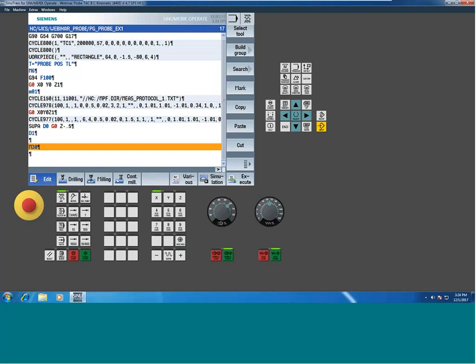From the CAM perspective, I get asked a lot about measuring a bore or a boss or aligning a fixture offset to the center of that feature. Can you discuss if that is possible and how the G-code would look? So that was probably written before I showed the measure command, or even just using some of the primitive commands. But keep in mind, if you're going to start to daisy chain multiple cycles together, that's where you're going to want to use the OVR variables. Grab the data and write that. But you can use any of our cycles in conjunction with any of the other ones.